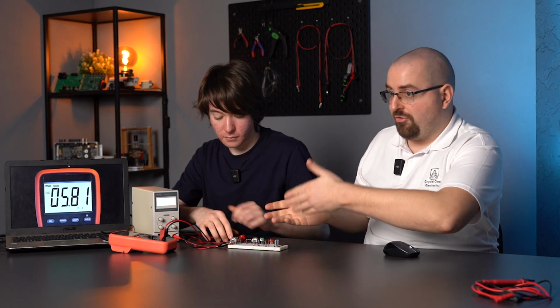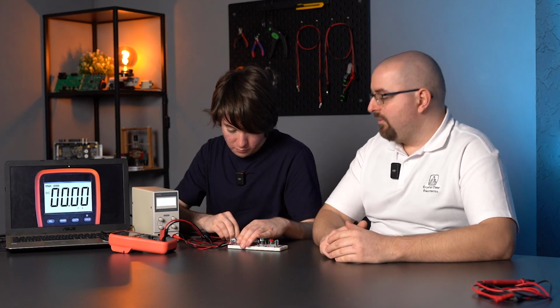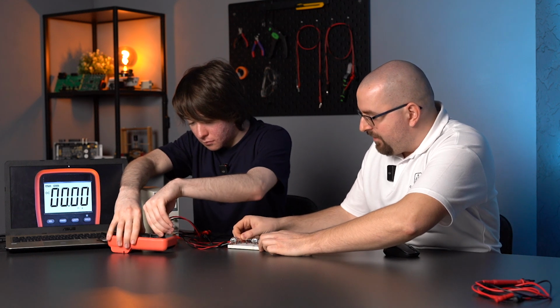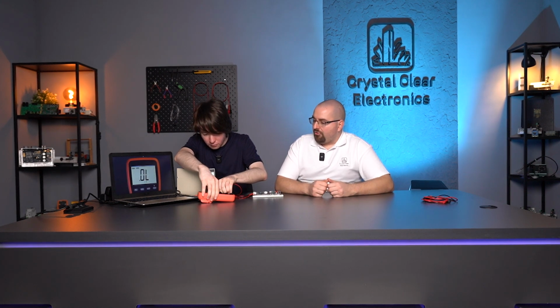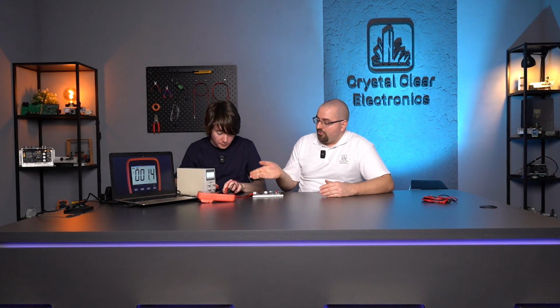We ask Marci to convert the current measurement into a voltage measurement. To do this, he has to disconnect the multimeter from the power supply. In the meantime, I'm putting the supply voltage back into the circuit. Very good, great! I turn the load to minimum and he switches the multimeter on to voltage measurement and connects the multimeter's test leads practically parallel to the diode, since that's also the output voltage of our stabilizing circuit. We want to see how this changes as the load changes.